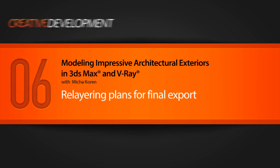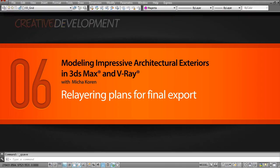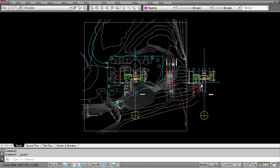In this lesson, we're going to look at a layering structure that will really simplify your modeling once you import this plan into 3D Max. Now, one of the key rules to remember is that when you click on a layer of 2D imported geometry in 3D Max, it's going to select every object on that layer as if it was one object. You will see this later once we pull all of this information into 3D in the next lesson.